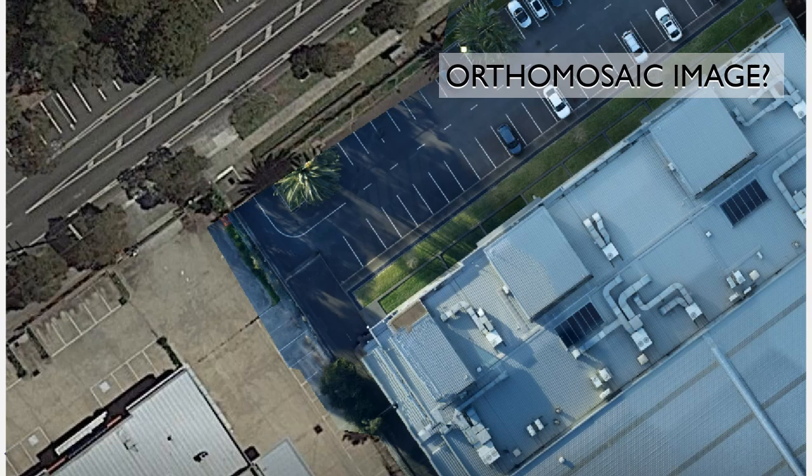If you're just stitching a group of photos together, you're not going to get the exact same image that you will through orthorectification. It does this by removing the perspective from each individual image to create consistency across the entire map while keeping the same level of detail from the original image.